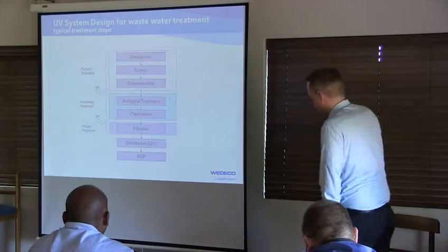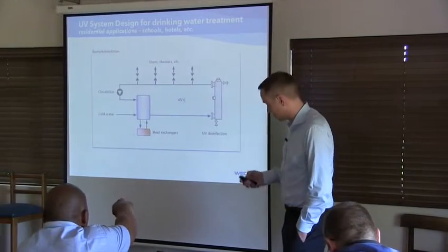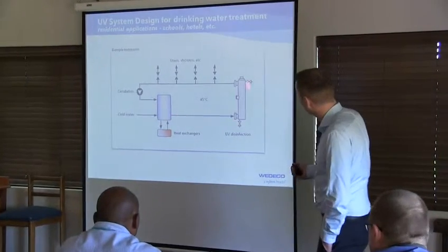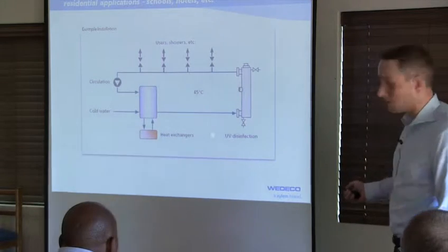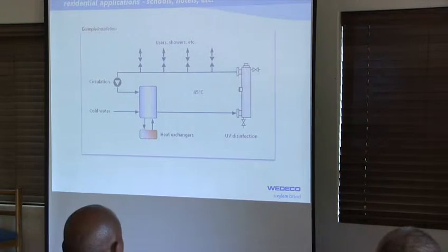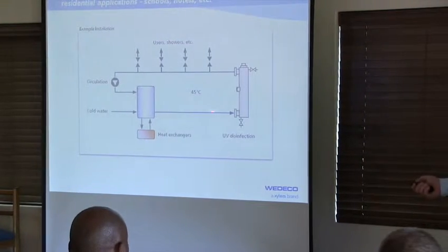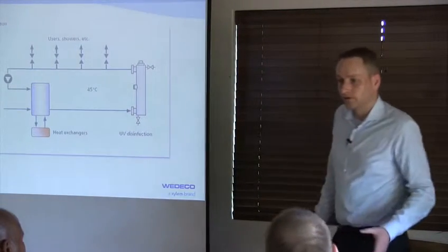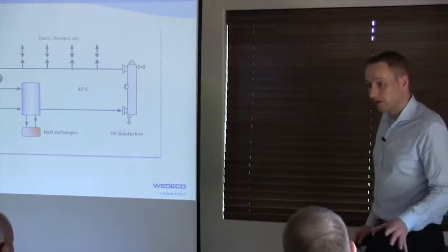For wastewater, UV, yeah. If you go a bit behind. Why don't we use the UV on the cold water line and do it after? We can use it on the cold water normally too, but this is just an example that we see in schools sometimes, or indoor swimming pools, because most UV systems are limited to water temperatures of about 30-35 degrees maybe.